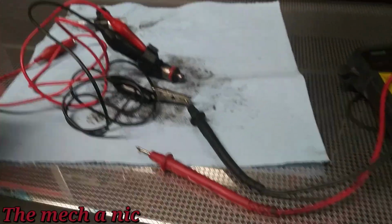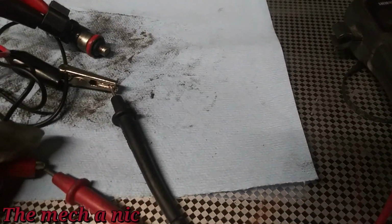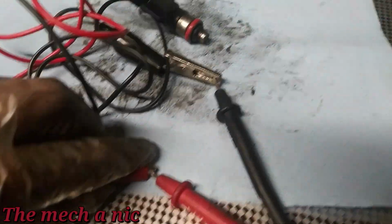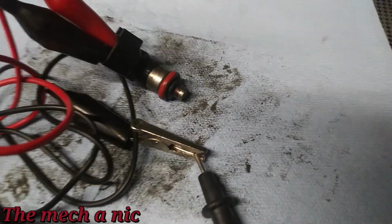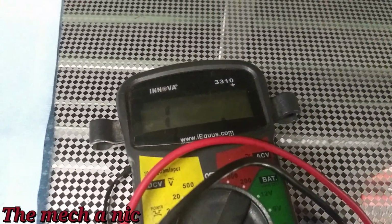Okay, so let me go ahead and put the test leads on the used fuel injector and see what we get. Okay, so I got the used or the old fuel injector connected, and when I touch this right here, alright, so that's making contact. This one's connected already. You can see it's clamped on, and we have nothing.